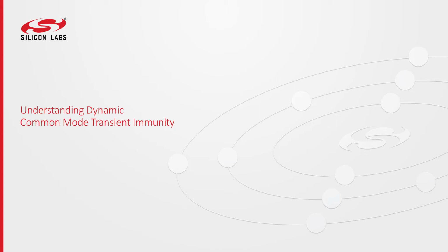This video provides an overview of common mode transient immunity, CMTI for short, and details the dynamic CMTI performance of Silicon Labs digital isolators. In this video, I will show both the dynamic CMTI performance of the SI84XX and 86XX digital isolators, as well as the SI87XX and 826X opto isolators and drivers, using a well-regarded, calibrated commercial CMTI tester.